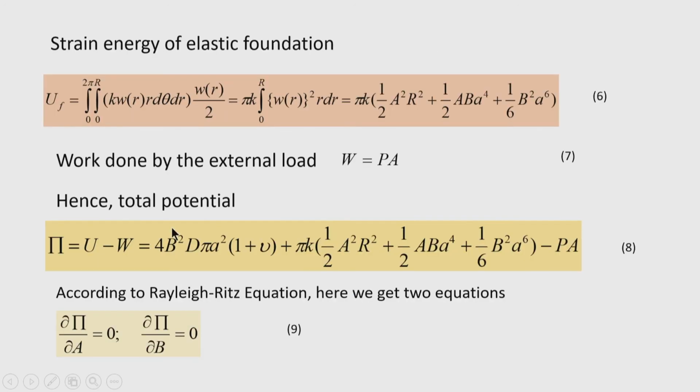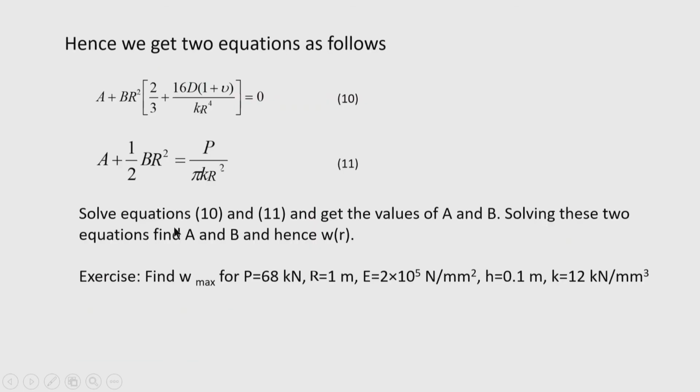This will be an approximate deflection, of course, because it may not satisfy the boundary conditions at the edges, which are very difficult: the edge moment as well as the edge shear both have to be 0, because it is the free end. Now, as an exercise you can calculate the numerical value for this plate problem.